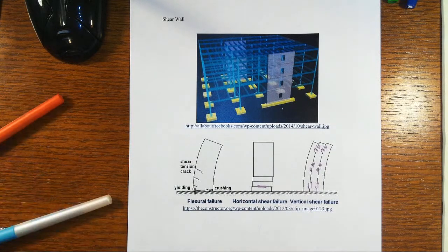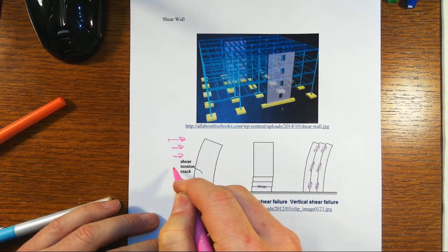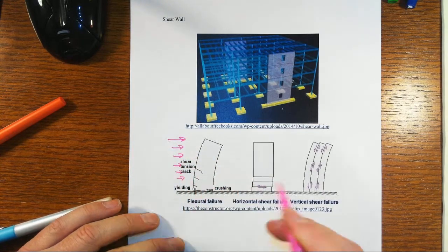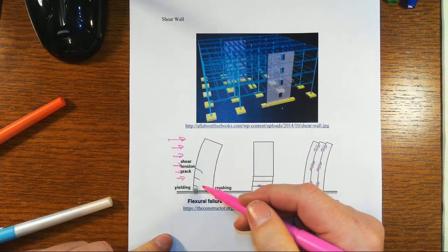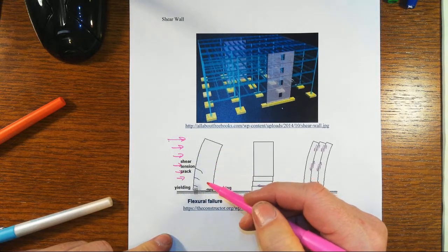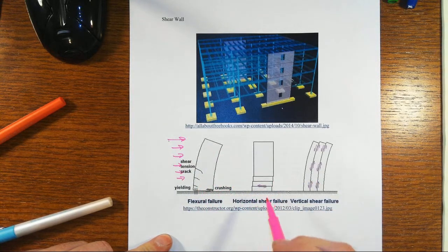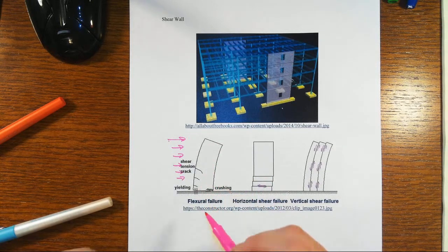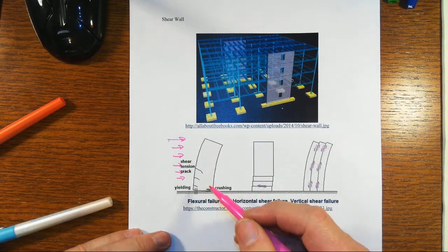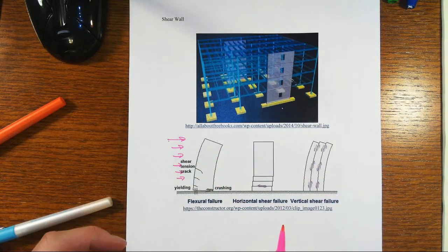And so the sort of interesting thing to me about a shear wall system is that as it responds to lateral loads, not only does it resist it through shear of this very deep beam that's sort of like a big gigantic flagpole, but it's of course much bigger. But not only does it resist in shear kinds of situations, but it also actually responds a bit like a cantilever beam. The cantilever beam now just being vertical like a flagpole.